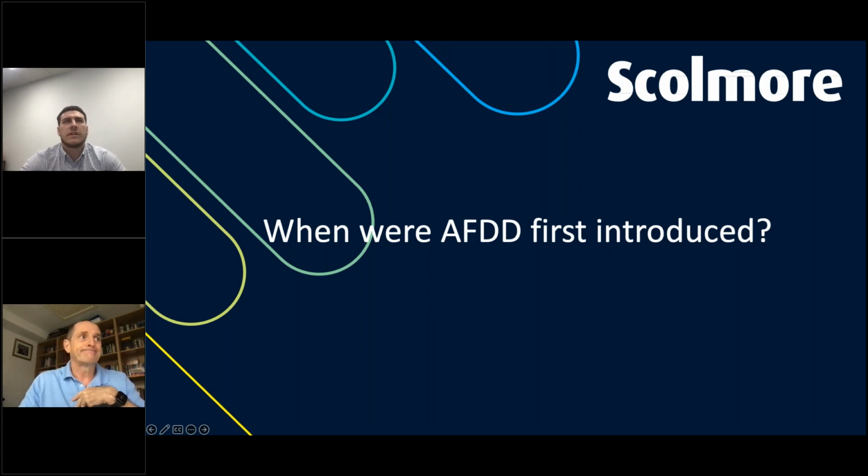So necessarily you couldn't really have them standalone, Tim. I know you mentioned that they work in conjunction with another device. Some contractors have had a conversation with us where they've said, well, why don't you use it the same way that you use an RCCB and group it together and look at a bank of circuits? I suppose in some ways you could, as long as you then doubled them up with a circuit breaker that was related to it.